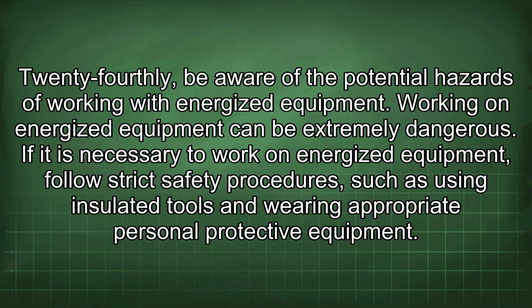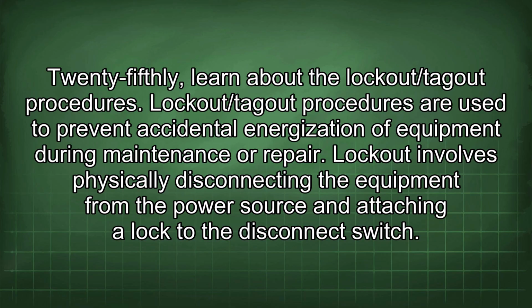24thly, be aware of the potential hazards of working with energized equipment. Working on energized equipment can be extremely dangerous. If it is necessary to work on energized equipment, follow strict safety procedures such as using insulated tools and wearing appropriate personal protective equipment. 25thly, learn about the lockout/tagout procedures.